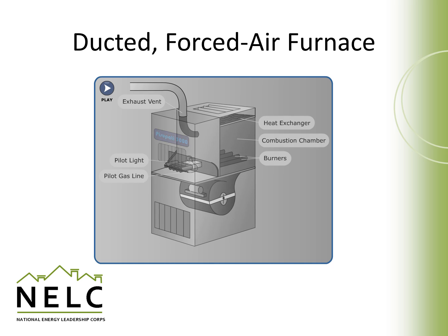Taking a look at how this actually works when it's in operation, when the thermostat tells the unit to come on, the burners will ignite and begin to get hot, and typically they'll take some time to heat up the burners and the combustion chambers, and only after they achieve a certain temperature will the fan come on.